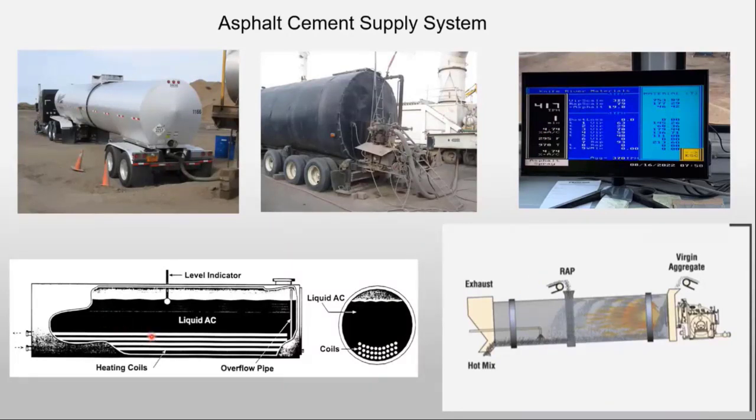This is just a schematic of one of these tanks. Up to this day, we still call it stick the tank, and we do that at the beginning and at the end of the day, so we know how much asphalt was used during the day. We can also keep track of it with the totalizer that will show up in the computer. Here at the bottom right is where the hot binder comes in, and it mixes with the hot superheated aggregate and wrap. That's where all the mixing takes place, maybe about 10, 15 feet, and then it's all ready to go out the delivery.